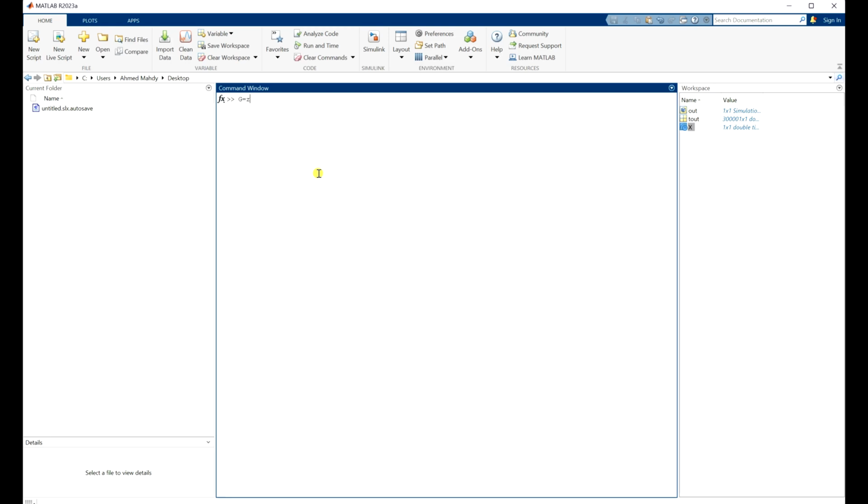and for this system I'm going to use another function, ZPK, similar to MATLAB Simulink: zeros, poles, and gain. Okay, so we have 3 values. How many zeros do you have? I don't have any zeros, so I will leave empty brackets. What is your gain? My gain is 1. How many poles do you have? Well, I have 3 poles. I have one at 0, one at -2, one at -3. And enter, so your G will be 1 over s, s plus 2, s plus 3.